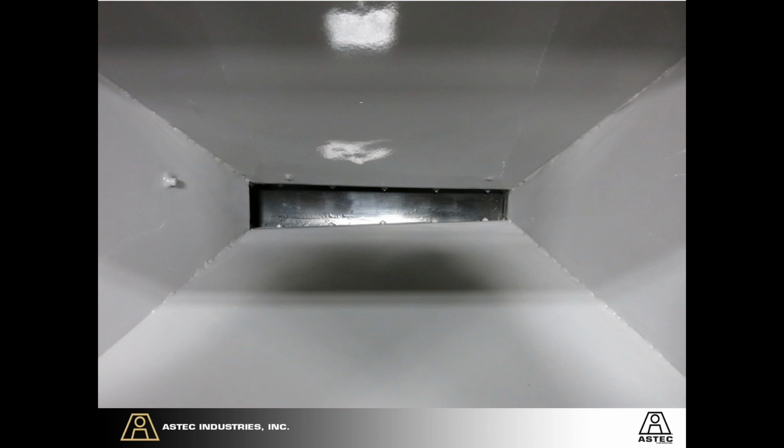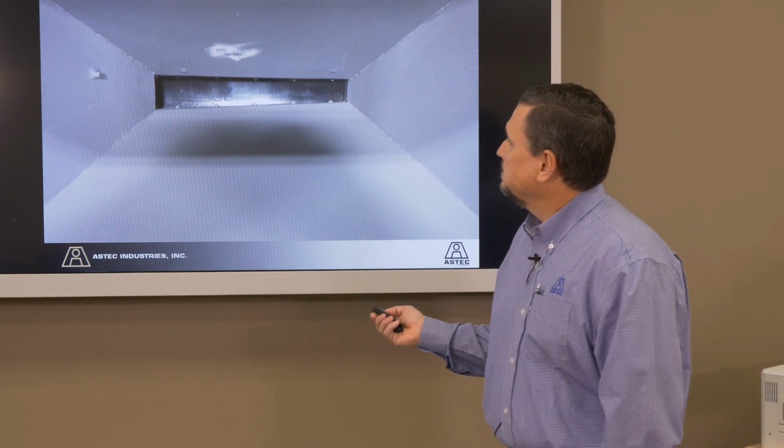If you take the grizzly off and look down into the bin itself, you'll see that at the rear of the bin you have an opening, and then as you move forward that bin opens up a little bit. What that means is that it's self-relieving. And so it does two things. One, it keeps the bin flowing well, and then two, it keeps the bin to fall evenly. You talk about segregation. Segregation in a co-feed bin, as long as you've got good material, should be minimal. But when you move to a recycle bin or something like that, and you're not fractionating RAP, it is very, very easy to segregate the material. So that is the reason for the self-relieving bin.